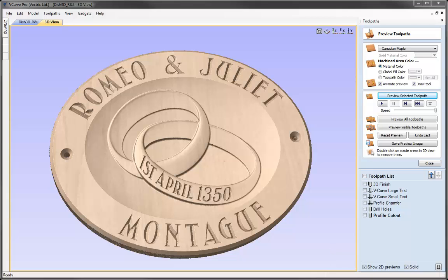So that concludes this example. Within this we've looked at a number of useful techniques and tips and tricks. You saw the right way to set up a dished object so that we have the zero plane both as a visual reference and also as a reference when we come to do the machining. We looked at how we can use the multiply effect with the different levels in order to taper down the edges of something and ensure that it will fit within a dish.